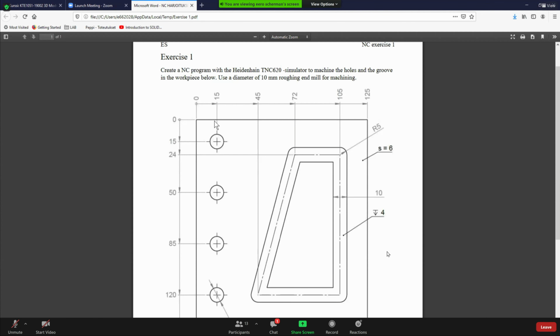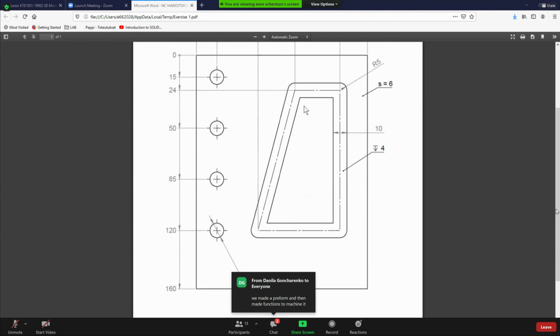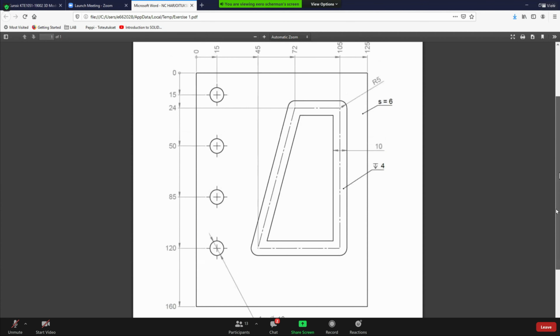Do you remember the basics, how it worked? What was the basic principle in the coding? Well, we had starting coordinates, and we just moved the tool and changed its height and changed the spindle speeds. X, Y, and Z coordinates, basically. Basically telling the tool to move in specific coordinates, and doing the movements and the spindle rotation achieve the desired outcome. I planned that maybe we could try to do this first exercise from last year's course, but with the help of CAM software. How does the result look like?